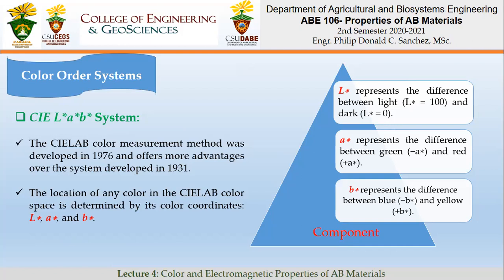So, the difference between Munsell, CIE, and CIELAB is that they measure the reference primary colors RGB, red, green, blue. However, their measurement methods are different. When it comes to CIELAB, what is measured is lightness, then greenness to redness, and yellowness to blueness, so it measures the saturation of the color. The CIELAB system, which is the most popular, commonly used color measurement system, can be measured using a handheld colorimeter. The handheld colorimeter automatically measures the L, A, and B values.